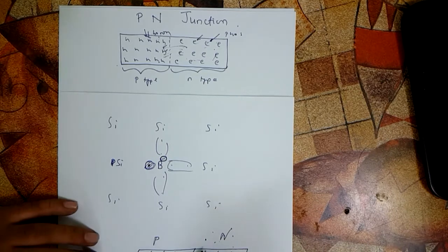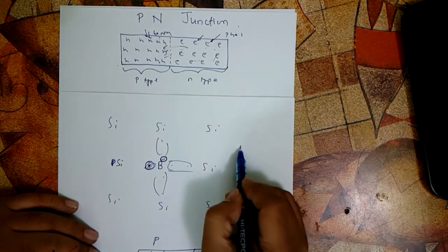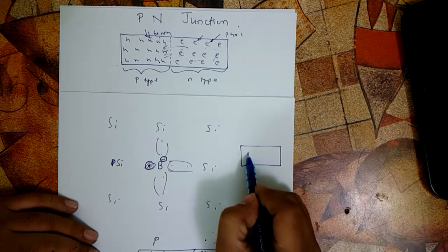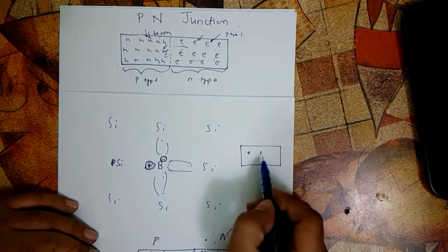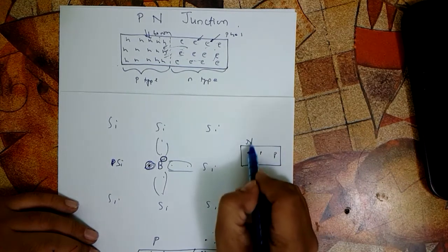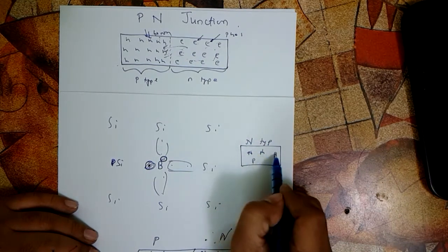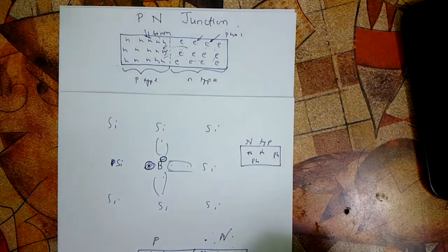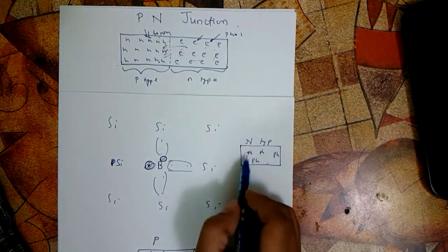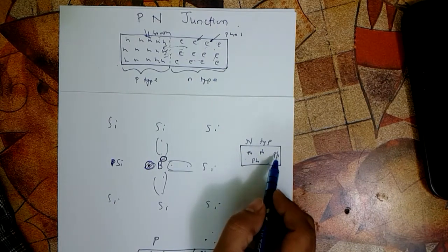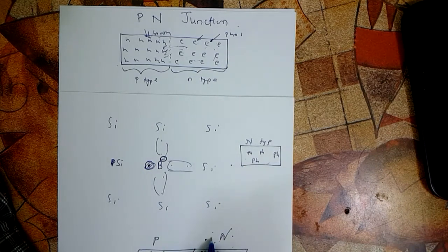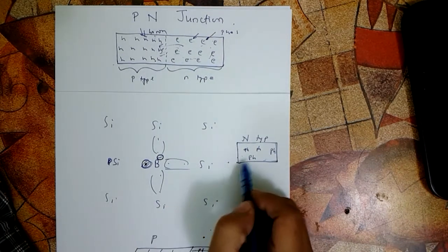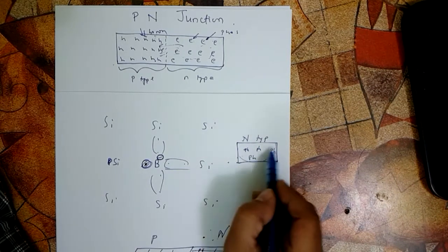All of these phosphorus atoms have given those electrons. Now when we have this n type only semiconductor, we know that once the electron leaves, those phosphorus will become positively charged. So shouldn't this n type semiconductor, because of this phosphorus, become positively charged because phosphorus has lost the electron? Well, overall it will be neutral, isn't it? Why? Because the electron which is given by the phosphorus is within the crystal lattice only. Obviously it is roaming here and there, but the electron is still there.